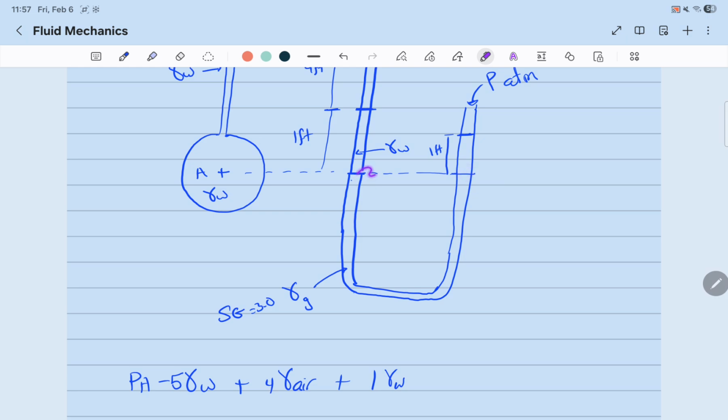If you take your finger and go from this point to that point, it's continuous and it's the same fluid. Therefore, we don't need to include all this. We can start right away from this point here, because the pressure at this point and this point is the same: it's the same fluid, at the same horizontal plane, and there are no barriers.